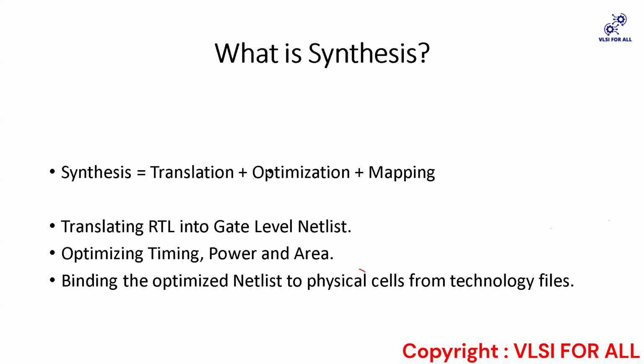Here in gate level compilation, first you need to understand what is compiling. It is the process of optimization. We use commands like compile or compile ultra. It has three steps: architectural, logical level, and gate level. In architectural level, it optimizes in such a way that the design is represented in GTECH format. In logical level, we need to remember that it is Boolean equation manipulation.